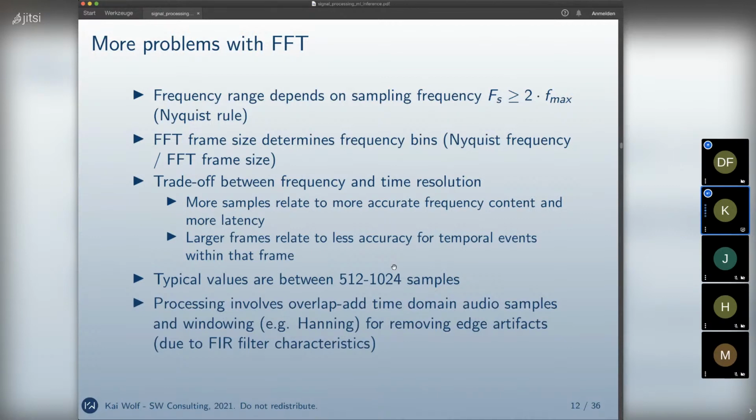And then finally, if we have done our work on the frequency, or have analyzed our frequencies, we do need to take back the inverse signal, so the inverse of the Fourier transformed signal, back into our audio stream. And since this is a FIR filter, so finite impulse response filter, we need to do some more audio processing so that it sounds natural. So this processing includes overlap adding in time domain. So we are gluing concurrent or neighboring time frames into one another, so that it doesn't introduce any artifacts due to the processing.